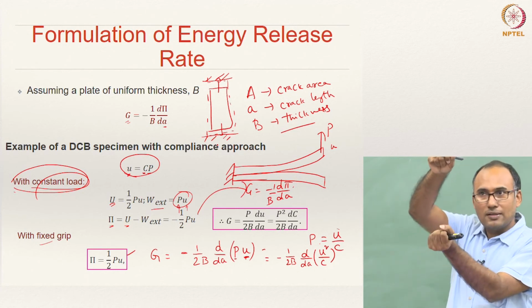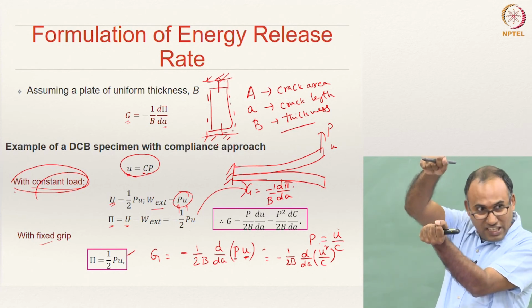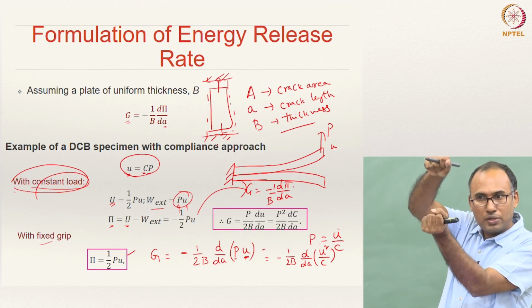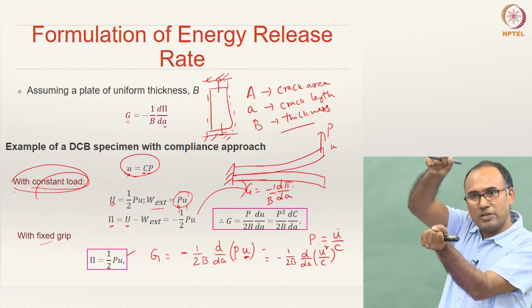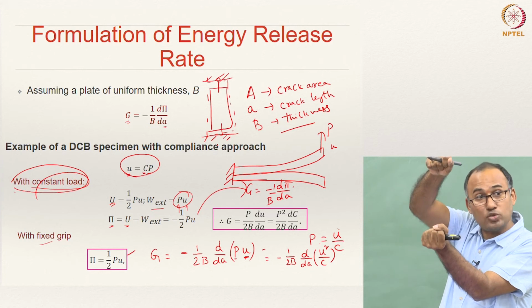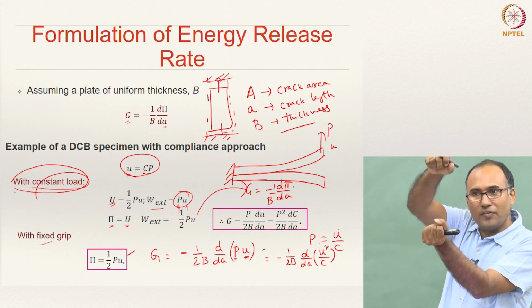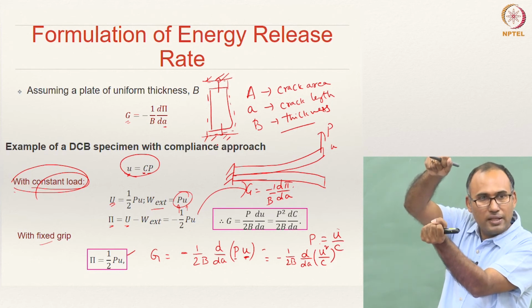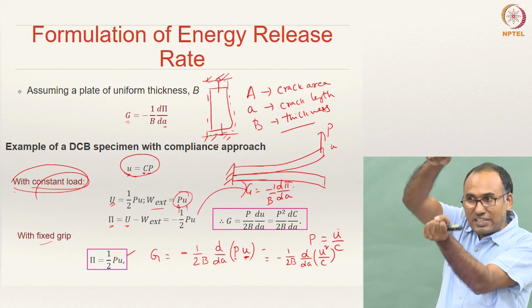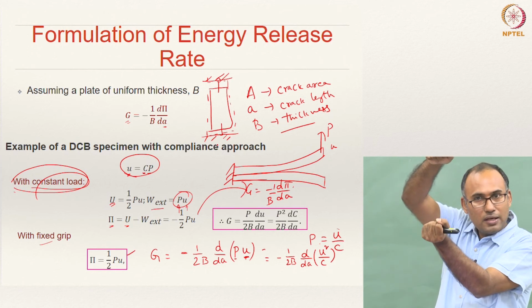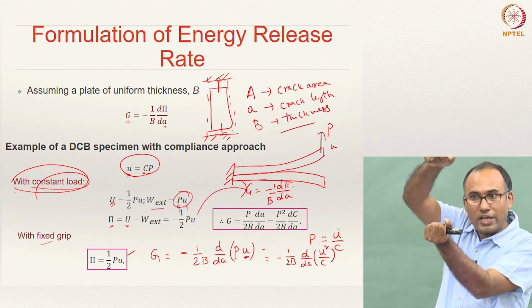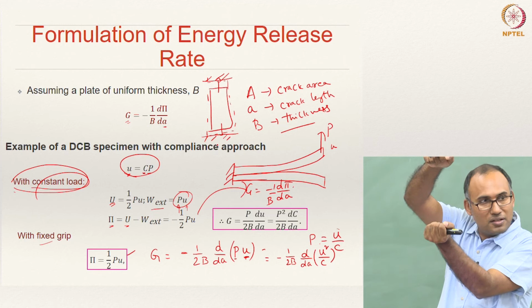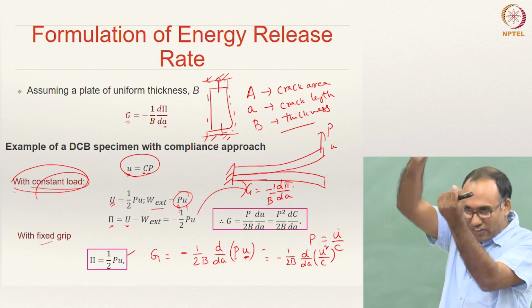So, imagine that now you have this body, you are holding at that displacement, and now you have a crack. If you are not changing the displacement, as the crack propagates, what happens to the force? When you are holding at this particular position, there will be some reaction force at this position, right? Here you are prescribing displacement. So, at the ends you will have reaction force, and as the crack is extending, what happens to that reaction force? It reduces, because the stiffness is reducing.